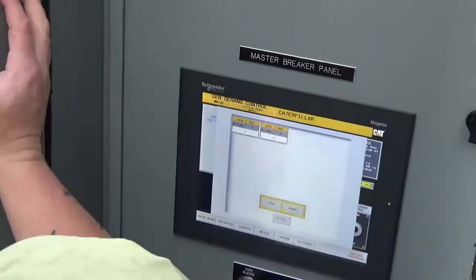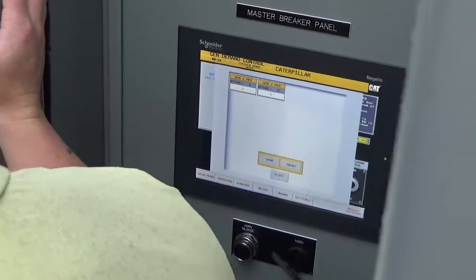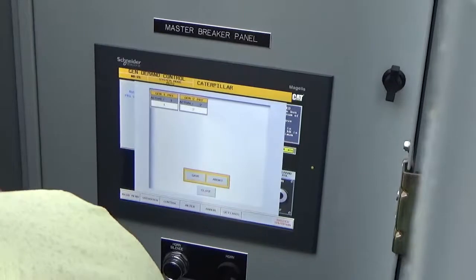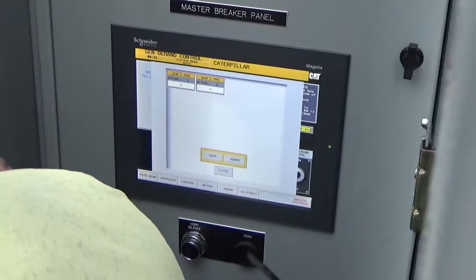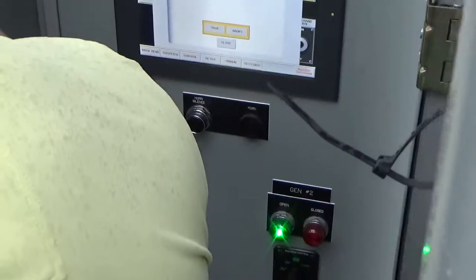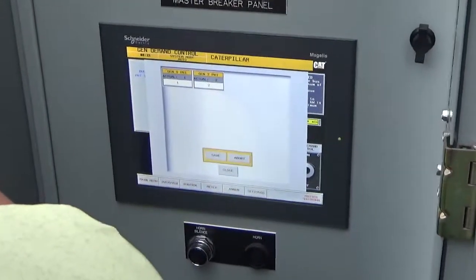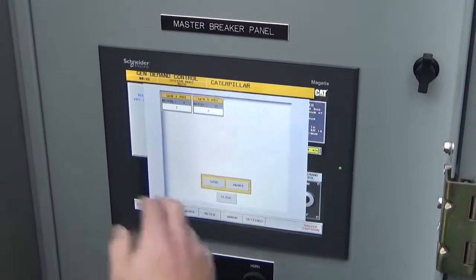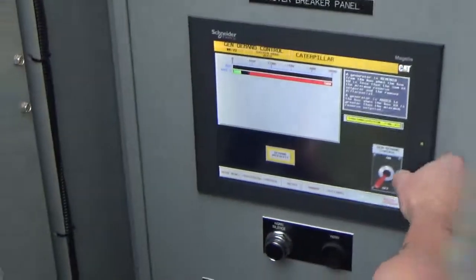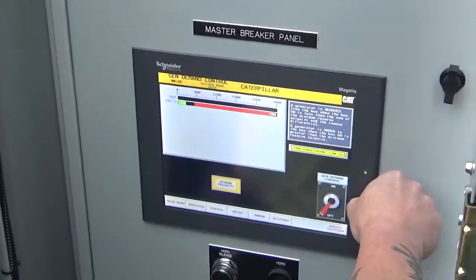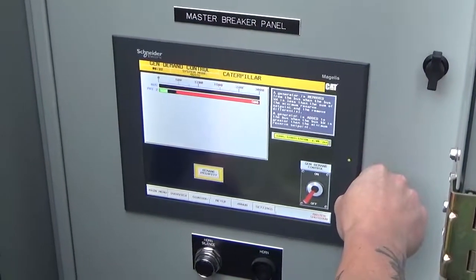What I'm worried about right now is the factory settings with those transfer switches. It could be 4 or 5 minutes before it rolls, especially if we're doing a monthly test or something like that. Right. So if you could go in for 5 minutes, or even 10. Okay. Better safe than sorry, right? But right now, if you look right here, the Gen Demand sensing is off. So it's not even going to run right now. It's not even going to use it until you need it.